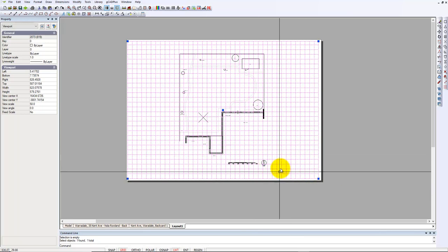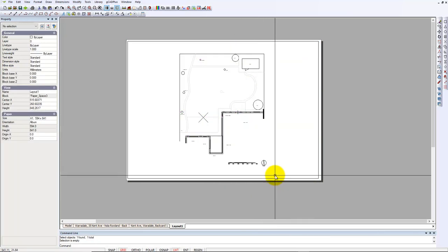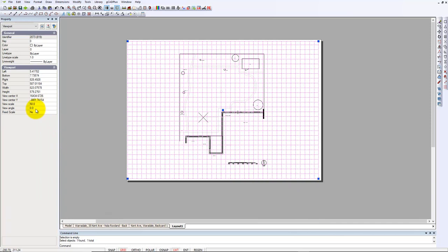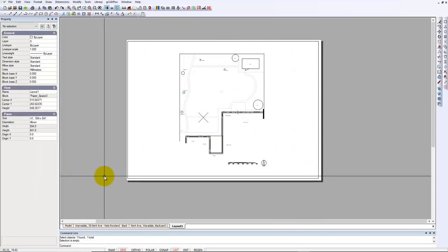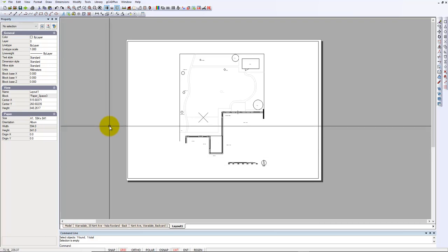I'm not going to bother with putting the title block down here, but let me just pick that floating viewport again, and I'll just make sure it's a fixed scale. So there's a porthole or a view, if you like, of the drawing, and when we print that one, we can print to an A1 sheet, and the resultant PDF will in fact be an A1 sheet.